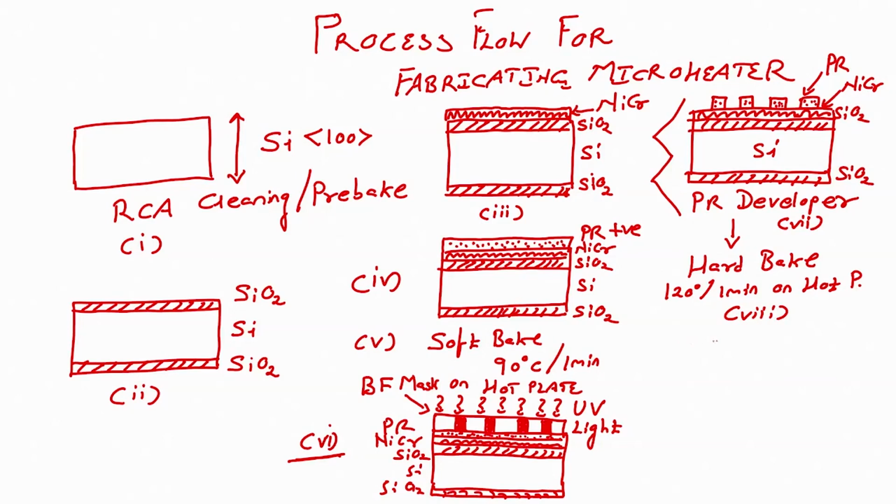After this I will dip this wafer, or I will perform wet etching by dipping the wafer in nichrome etchant. After this what will I have? I will have a wafer,